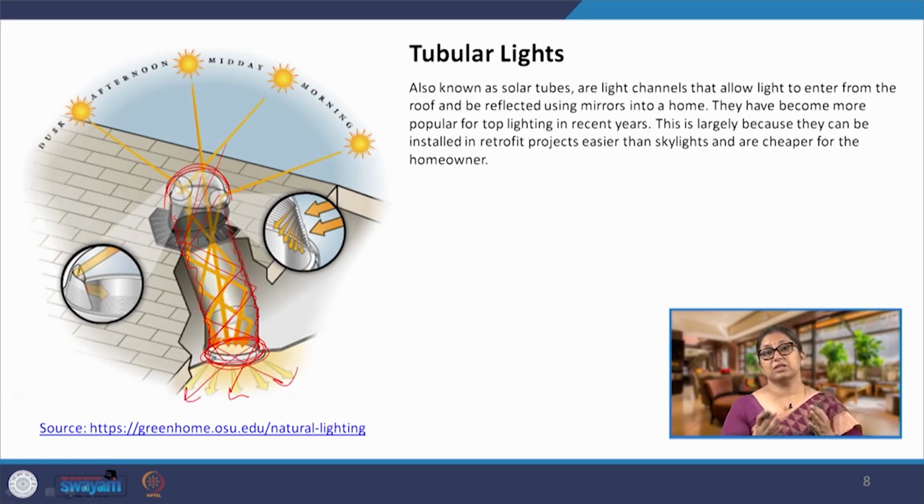If you look at the light pipes or these tubular lights from inside, one may not be able to figure out that this is actually not an electricity fed light, artificial light. It is not natural, it is a passive design feature, but it allows us to bring light into deeper areas. But the limitation with this one is that we can use it only in the floors where we have a roof above, or at max we can take it a floor below.